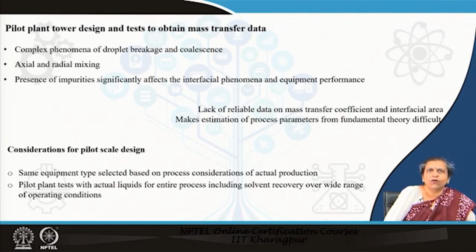Quite naturally, due to all these things, there is a lack of reliable data on both mass transfer coefficient as well as interfacial area. As a result, the estimation of process parameters from the fundamental theory, that is from the basic mass transfer equations, the equations which you have learnt in your mass transfer class, is extremely difficult. And so, naturally, in order to obtain data on the mass transfer coefficient as well as on the interfacial area, generally we perform the tests in the pilot plant.